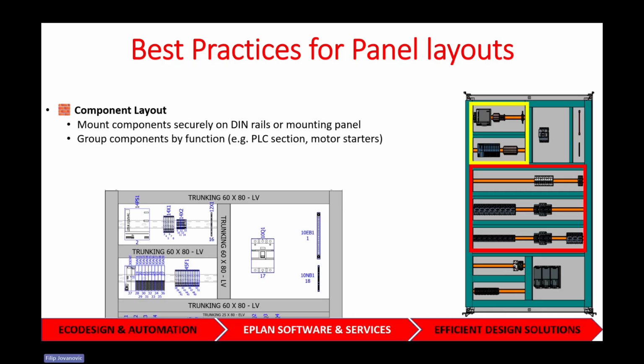It's also a good idea to group components by their function. So, for example, you don't want your motor starters to interfere with the PLC section, stuff like that. And you want to keep heat generating components separated. So stuff like your VSD, which is going to be your big one. You don't want your VSDs to blow hot air into a PLC or an Ethernet switch.